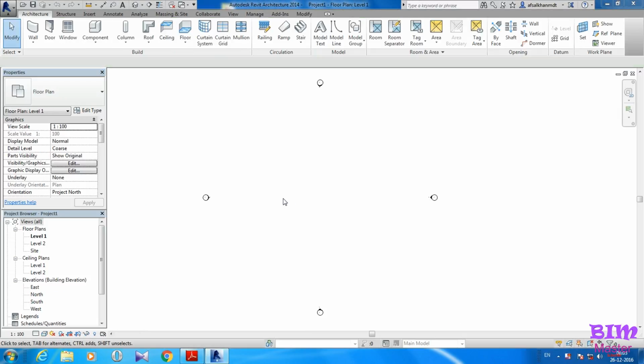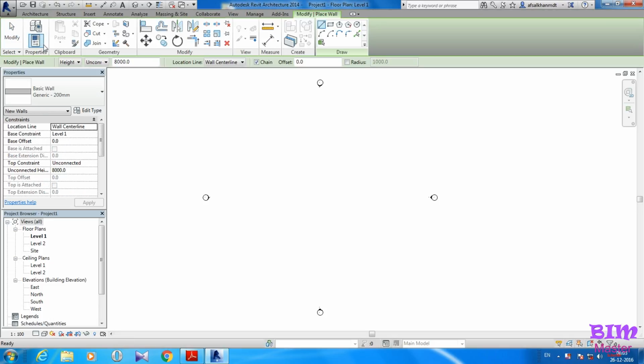Then now we can go to the second main subtopic: creating numerous wall configurations. Let's start adding some walls to the current project. First, open the Level 1 floor plan view, and click the Wall command. Notice in the ribbon on the Draw panel that a number of configurations are available for creating walls. You can see a variety of options for sketching wall segments as well as 2 icons with arrows that indicate options you can choose from to pick line segments on which to place walls.